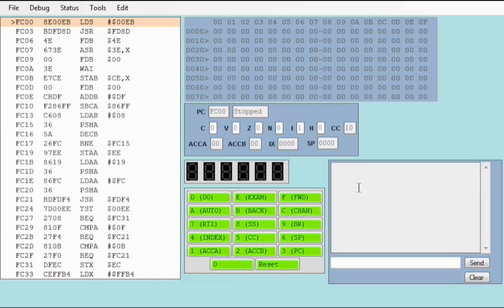The most significant upgrade is that the expansion has a serial port in it, because both the new monitor and the basic interpreter cannot possibly be run on a 6-digit 7-segment display. So what you do with that, once you had that installed, you hooked it up to a terminal and you typed away on your terminal rather than the hex keypad, and you received your output through the terminal rather than the 7-segment displays.